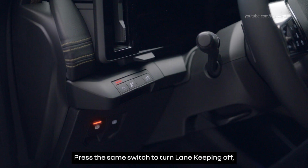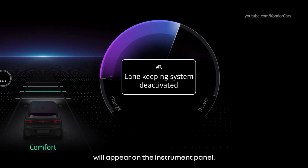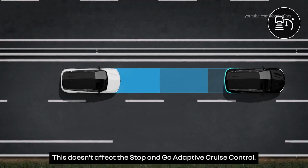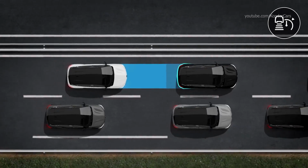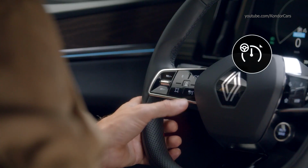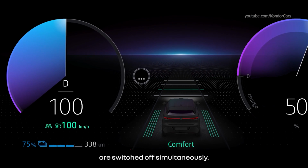Press the same switch to turn lane keeping off, and the message "Lane keeping off" will appear on the instrument panel. This doesn't affect the stop-and-go adaptive cruise control. Lastly, press this switch to turn off Active Driver Assist. Stop-and-go adaptive cruise control and lane keeping are switched off simultaneously.